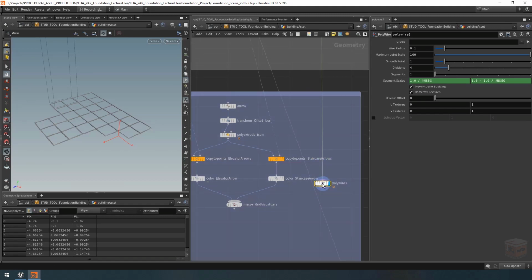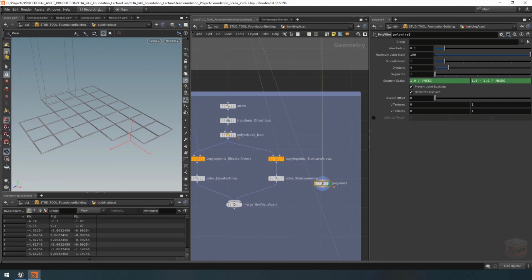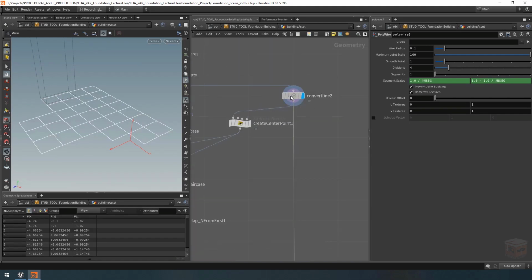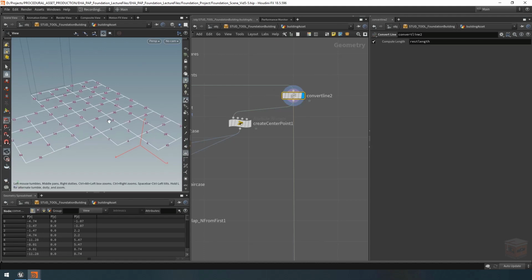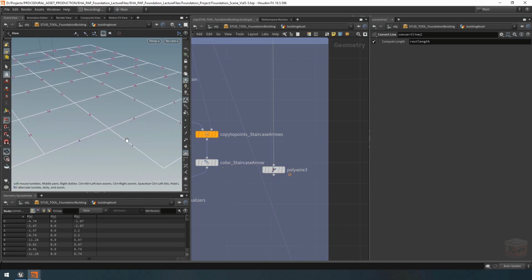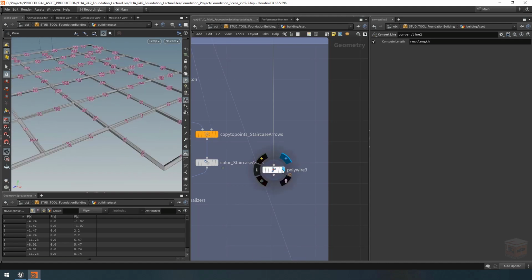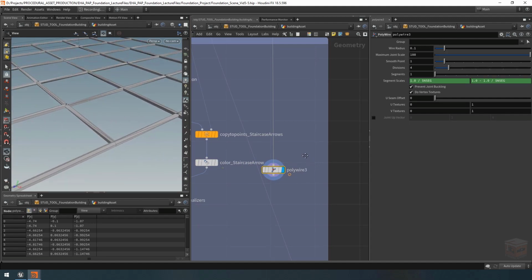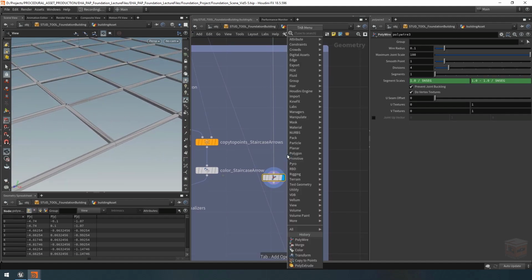Now instead of getting all complicated with how this is generated, I'm just going to disconnect every single one of the points in between these polylines. And if I do that, then it will generate one solid mesh for every single line without trying to fuse them in the middle points. And this will actually create a better, cleaner result for us. So let's create a unique points node.